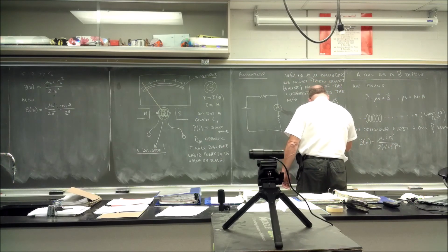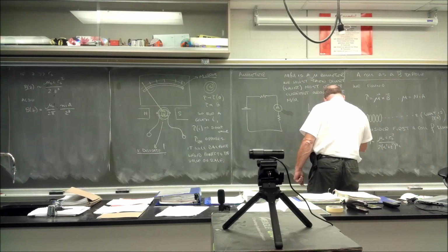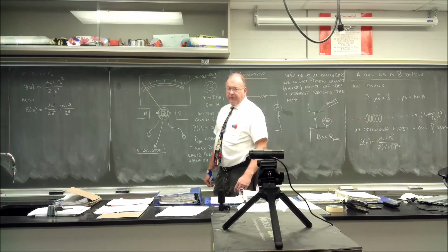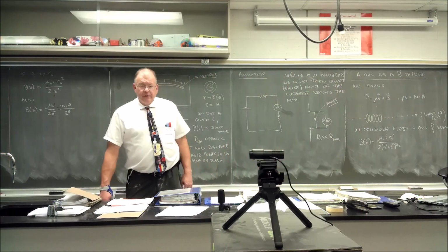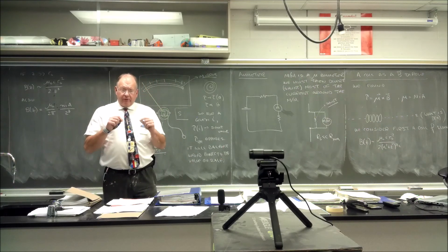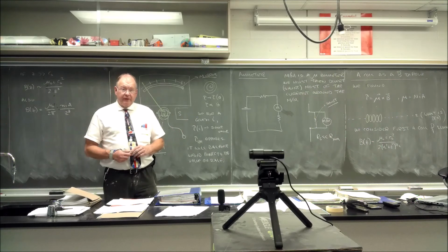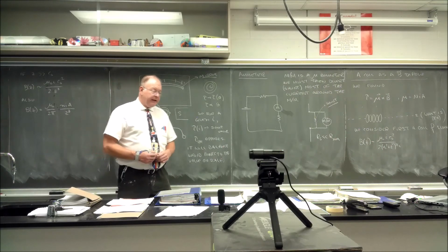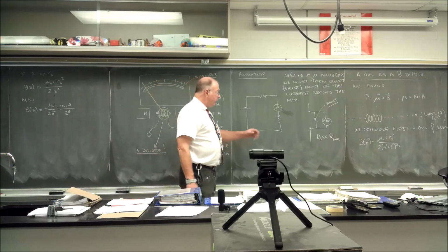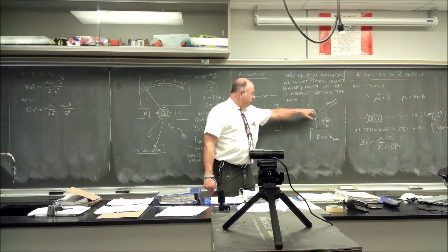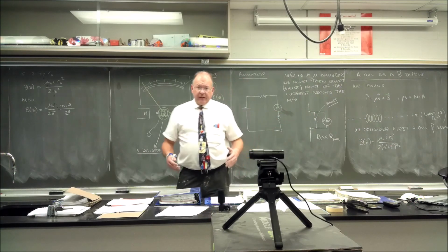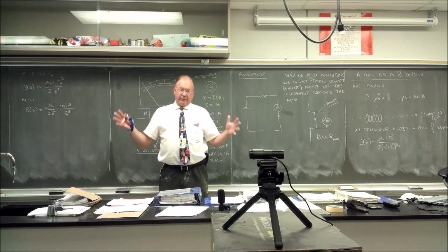So our shunt is less than the resistance of the meter. Shunt resistors often are misunderstood in meters. If you look at them, they look like wires, or even big wires sometimes, or coiled wires, because they're designed to have low resistance, which is a wire often, and which will take a proportional amount of the current away and preserve the meter. If you have a meter with multiple ranges, it just means that when you rotate the switch, you're choosing whichever resistor makes sense for the range you want. If it says 10 amps, that means the maximum safe measurement is 10 amps.